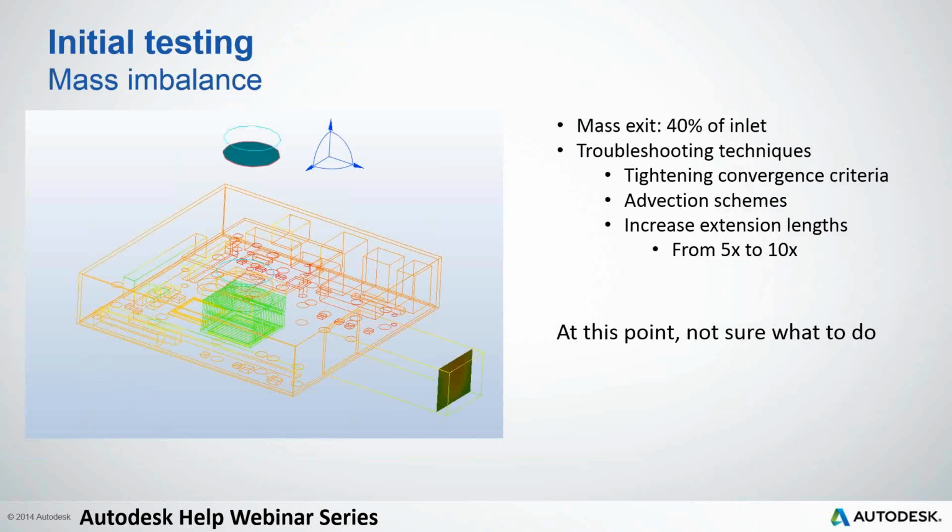So initial testing, once I had this thing put together, I used a cut plane on the inlet and outlet and used the bulk calculator to check the mass balance. I included this because it's actually an issue. I ran into quite a bit of trouble here and chased it for a lot of time and wasn't sure